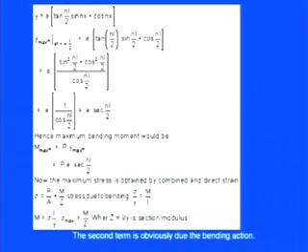So we can say e tan nL/2 sin nL/2 plus cos nL/2, or if we simply manipulate, sin square nL/2 plus cos square nL/2 divided by cos of nL/2. We simply change tan to sin over cos, and sin square plus cos square is 1. So we have the maximum deflection exactly at the midpoint of that particular strut, x equals L by 2.